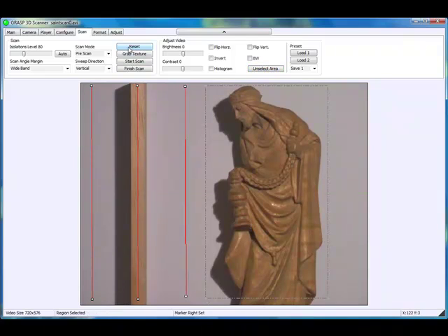The next step is to press the Scan Reset button, which will initialize the scan for processing of the recorded video. The Grab Texture button is pressed and the texture is captured. This may take a moment to complete since Grasp stacks several pictures into one. This is done to minimize video noise by statistically filtering the captured frames. It may be also helpful to use the histogram in the Adjust Video group box in case you want to better balance out the picture levels.